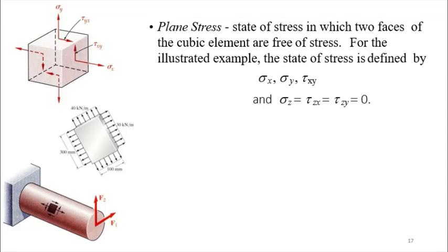So first we need to understand what is plane stress. Plane stress is a state of stress in which two faces of the cubic element are free of stress. So remember, I mentioned, let's say the front surface here is on the surface of the object. Therefore, there are no stresses on that surface. Similarly, on the rear surface at the back, there will be no stresses as well.